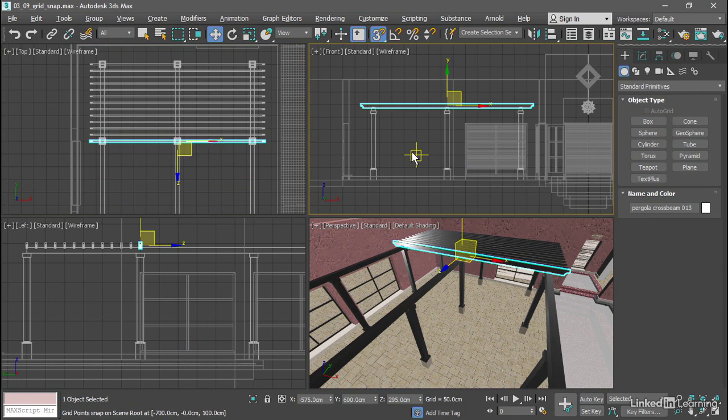There are two ways to work around this: 2.5D mode and axis constraints. Let's look at 2.5D mode first. Click and hold the Snaps button to get the flyout and choose 2.5D mode. This is going to move the snap cursor in the 2D space of the screen itself, also known as the picture plane. So just to give you a little bit of background information, rendering, or the display of an image, is the projection of the 3D scene into the flat space of the image, in this case a viewport.